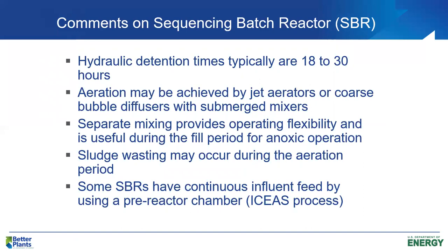Again, overall detention time is about 24 hours. So again, it's low rate activated sludge. We use jet aeration or diffused aeration. The process is flexible. Again, we can incorporate anaerobic and anoxic zones or modes in the overall cycle, and we can produce outstanding effluent quality. And this biomass actually settles extremely well because it's not a continuous flow secondary clarifier. It's a batch settling tank. When the influent is shut off, we get excellent settling during the quiescent period of the settle phase.